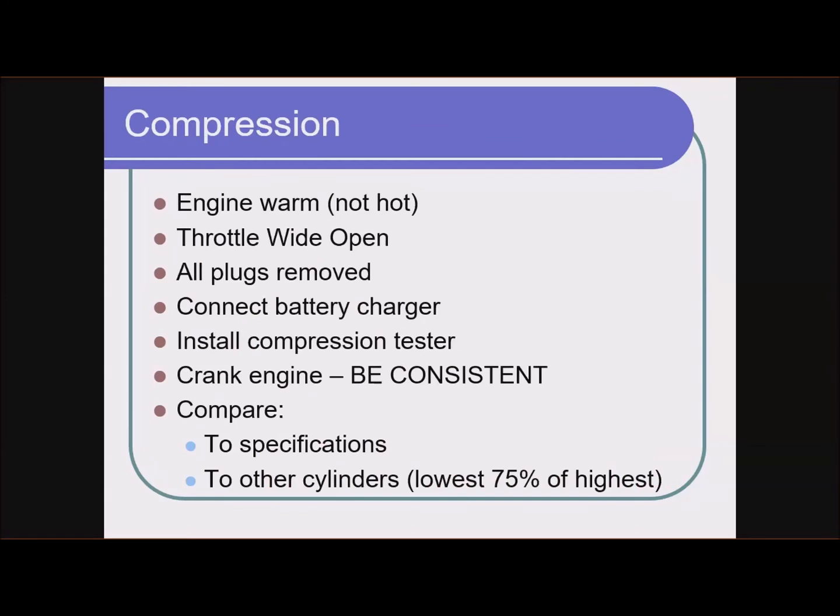And I think it might have been a Honda this semester where there was a really significant difference in the compression pressure we got when we didn't open the throttle. The numbers were way lower than they were with the throttle wide open. So that's kind of convinced me that regardless of the vehicle, I want to have the throttle wide open during a compression test.